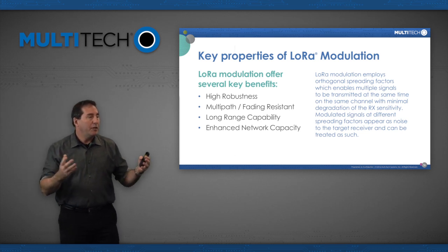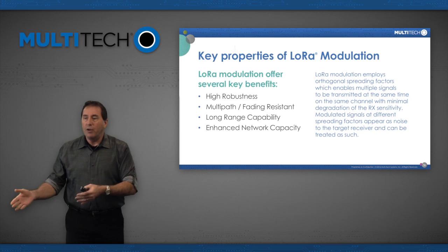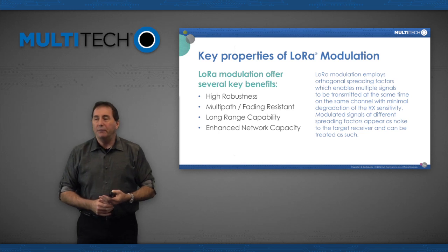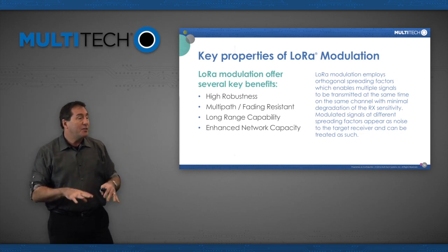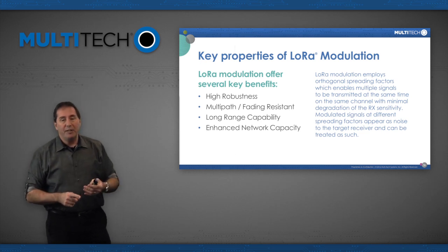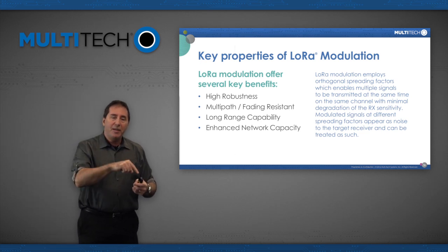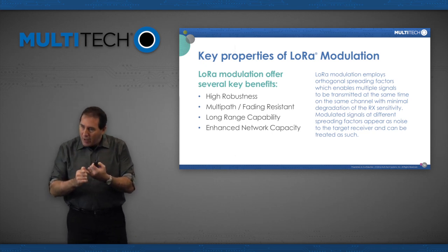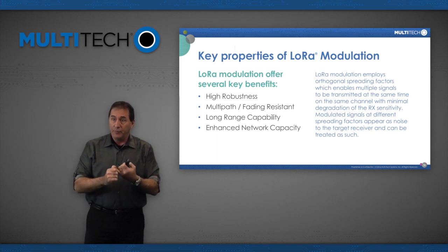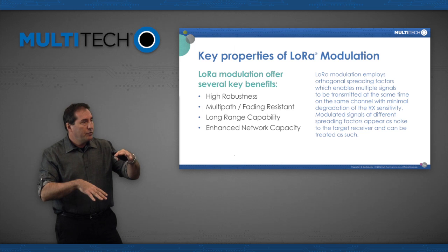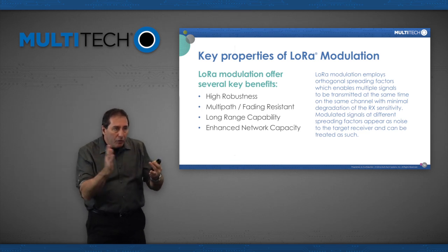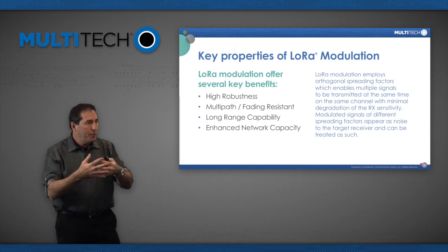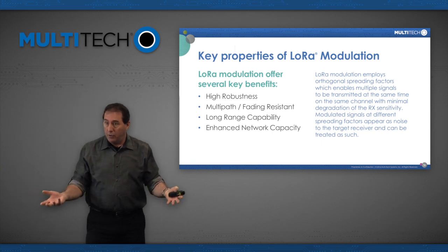So people are saying, hey, LoRa is an Aloha network, so all you're ever going to get is 18% of your total available bit rate. And the answer is, today, yes, that's kind of true. Except there are other factors that make that argument not quite right. One factor is that LoRaWAN has an automatic data rate function. It controls endpoints and the channel they use and how they talk, to allow more people to talk than you would normally have in a regular Aloha network.